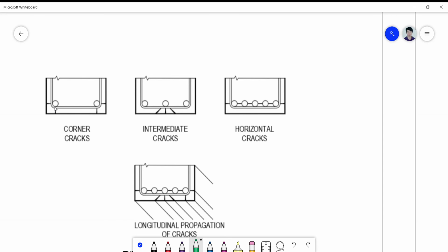You can see now from the inside there's a crack, and then it will manifest eventually to the outside. So the splitting cracks must originate from the reinforcement surface because of the deformation.